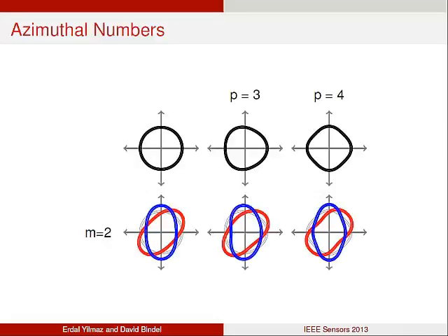In order to understand why it happens, we first have to have a way of describing these vibration modes and the perturbation modes. For an axisymmetric device, the natural way of doing this is using Fourier analysis. For the vibration modes that we have looked at here, we have radial displacements like cosine 2 theta. So we say that this vibration mode has an azimuthal number m equals 2.